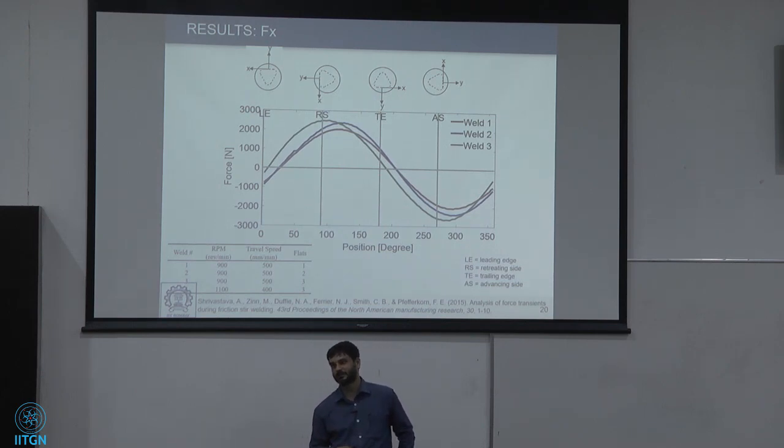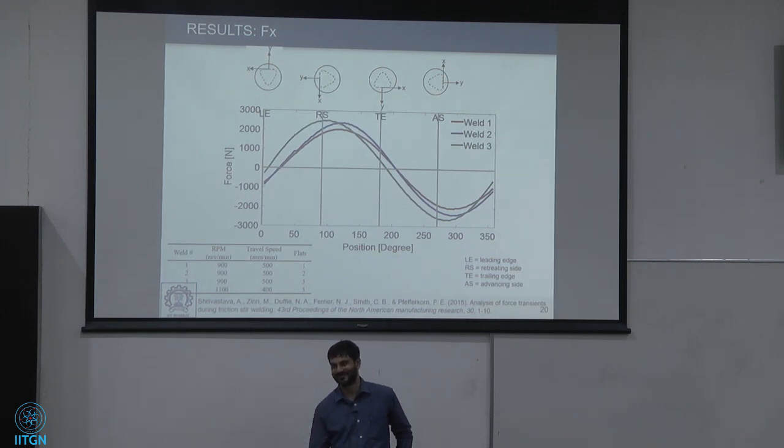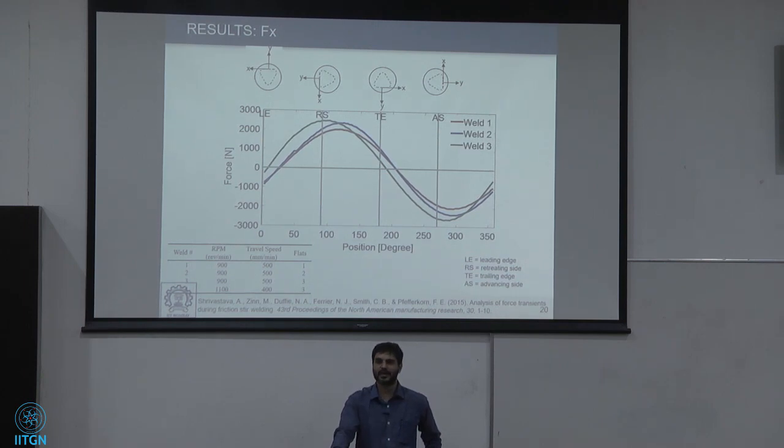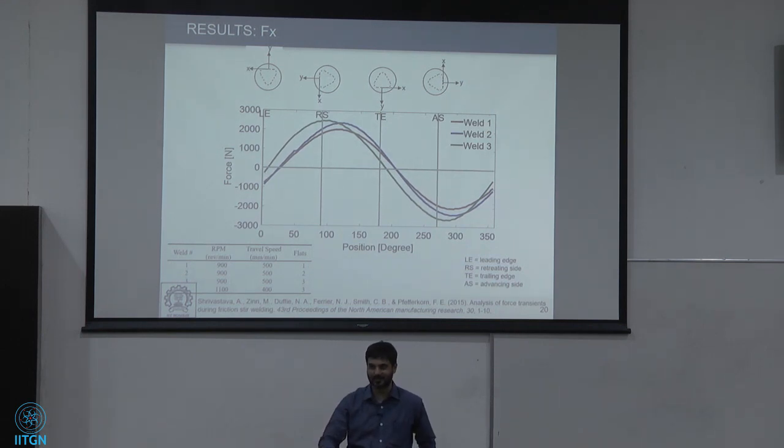Then have you filtered the data? Because I would imagine the dynamo data to be very noisy. So dynamo data was not filtered afterwards. In this plot, are they filtered? Because sometimes, depending on what filter you choose, you can get a lead or lag. Correct. Right. So there was no additional filtering which was introduced in these.